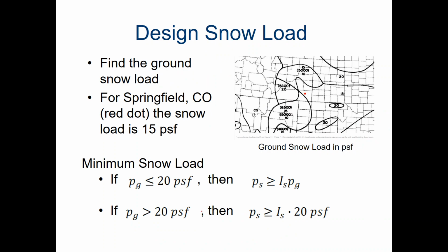These here are some modifiers, and so what the building code does is it wants to make sure that everything is super duper safe. And so they have these checks and balances. And so when we go to do the actual assignment, we'll go a little bit deeper into here. But what this is saying is that your design snow load needs to be modified based on certain conditions. And you just need to check these things out and make sure that you're within these parameters.